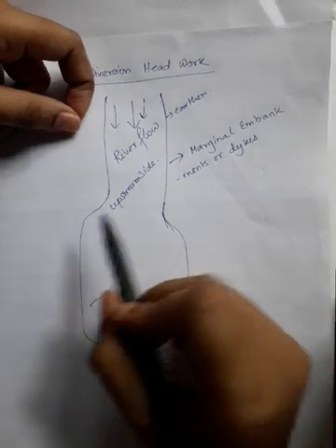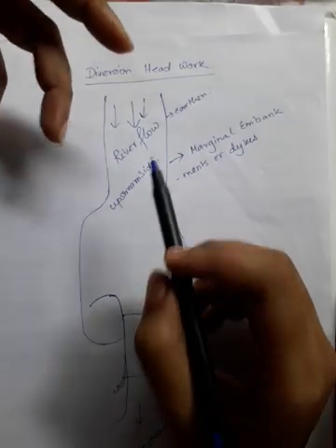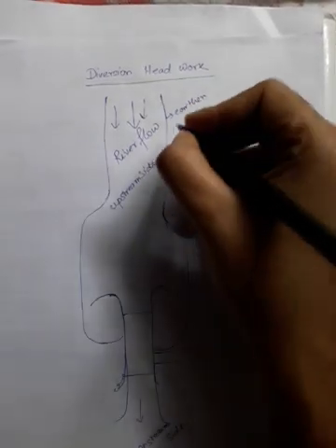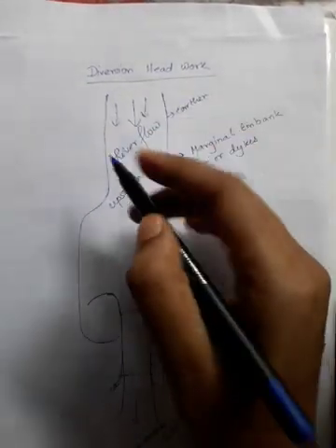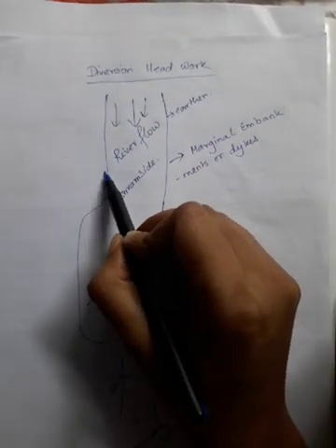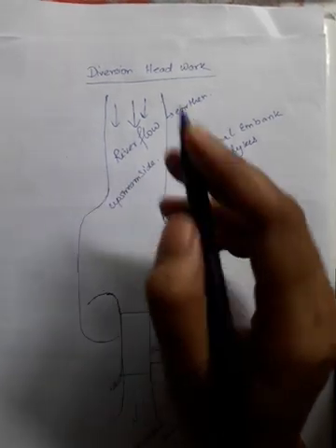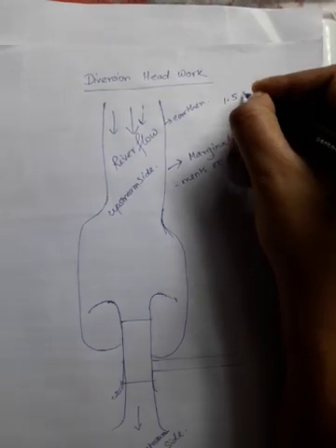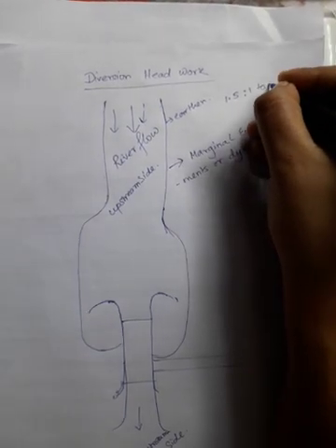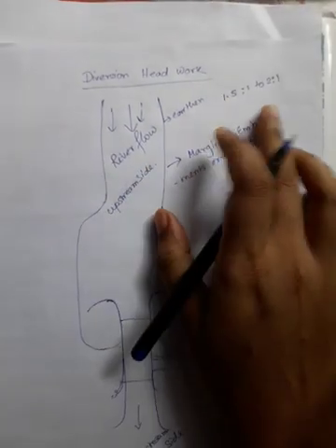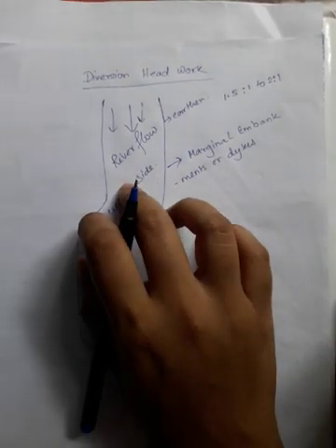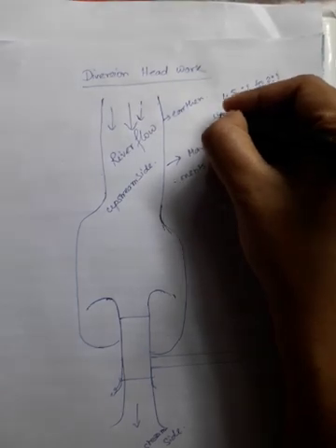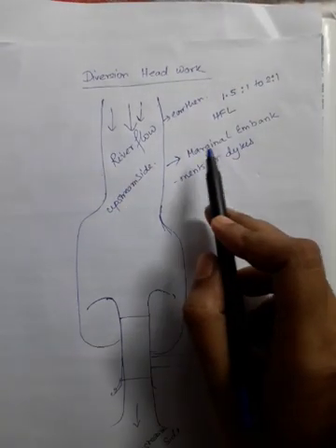Basically the top width of the side could be 3 to 4 meters, and the slope of these dikes is generally 1.5:1 to 2:1. This also depends on the height of HFL, meaning the highest flood level.